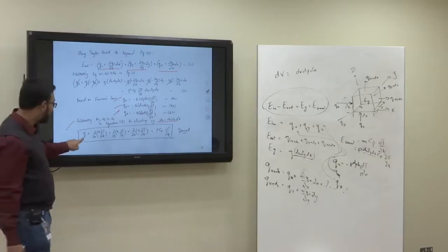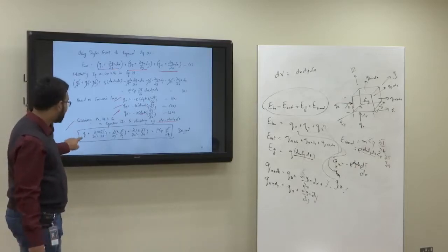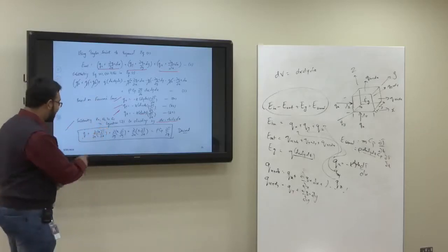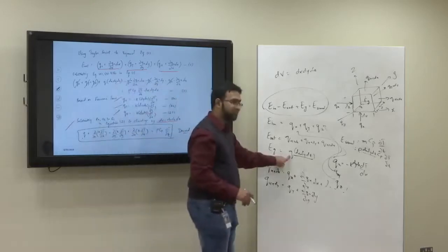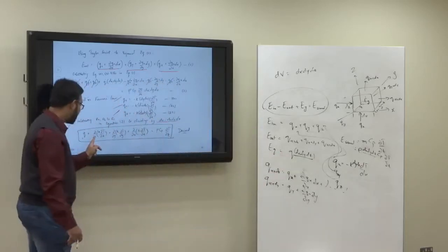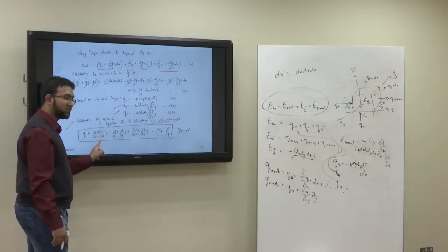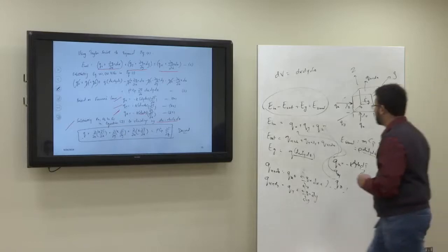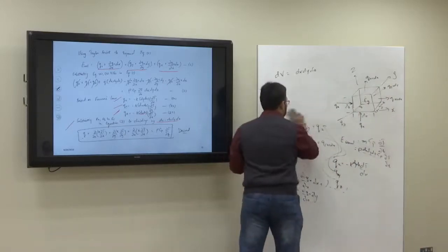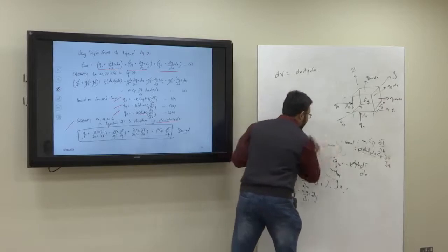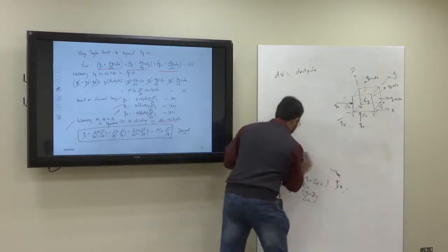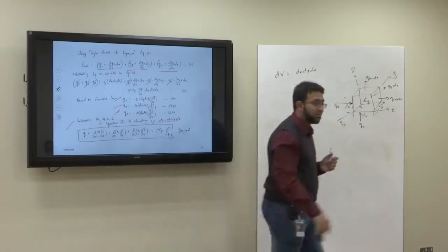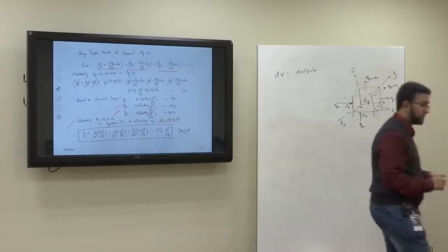So you will have Q dot, remember it was energy generated per unit volume, plus dou by dou x of k dT by dx. This is the main equation, important for the next 3 chapters: chapters number 3, 4, and 5.